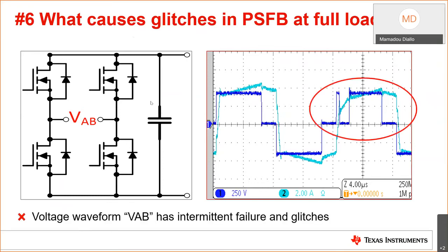All right. It looks like some of you guys picked noise coupling from the gate drive portion. Yes, that could be a possible root cause. And signals on the driver's input may be beyond ABS max. That could also be a factor, though option A will likely damage the driver altogether.